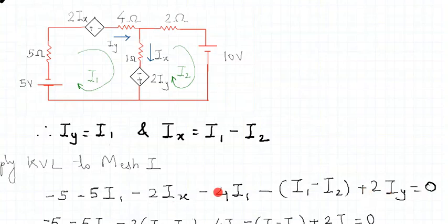If you are correctly formulating this equation, then you have applied KVL correctly, you have understood KVL correctly. What is important is the signs, the signs that you have assigned. If you make a mistake in that, then your equation is wrong, and your further values will be wrong. So what is important is the polarities when you are formulating the equation. I hope this is clear to you.